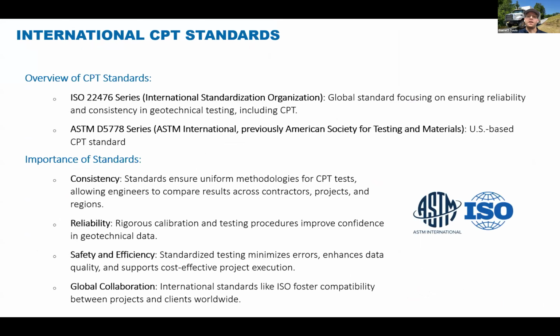Moving on to the standards that govern CPT testing across the world. We've got ISO 22476 internationally, and here in North America, the standard for CPT is governed by ASTM D5778. As we know, these standards define procedures, calibration, and reporting, and by adhering to them, it allows for comparable and repeatable data.